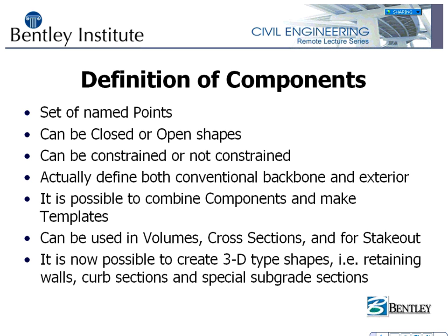It's possible to define both conventional backbone and exterior with these. So those of you that are familiar with our backbone class and our side slope class, these are where you actually do the backbone and the side slope, except now it's possible to combine these components and make templates. So we've kind of broken it down where at first it may look difficult, but after you use this a little bit, you'll much prefer using a component approach versus a template that has to contain everything.